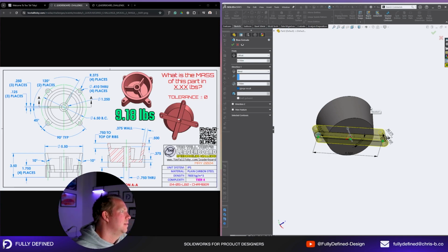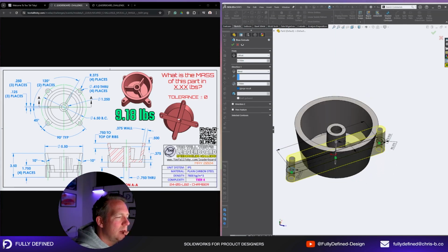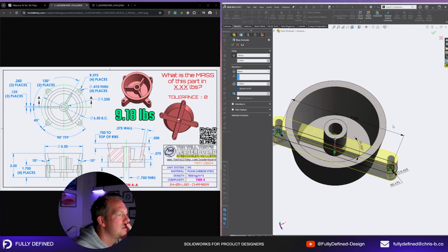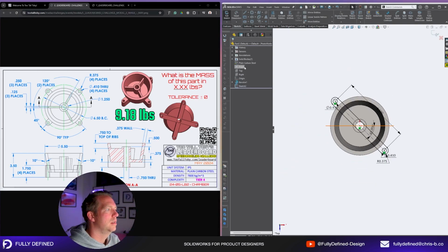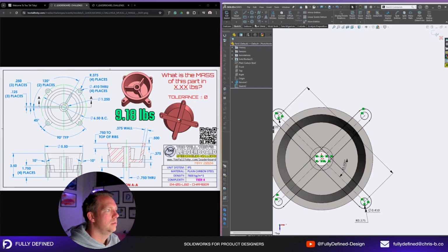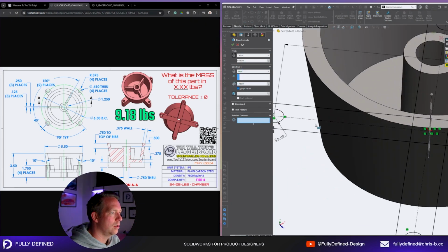Yeah, it's actually a nice complicated model to think about. Yeah, it's a tricky one. I'd really like to go extrude up to next, but up to next won't cut it because it stops at a certain distance. So that won't work. I think we have to go multi-body then and just cut that hole again afterwards, in which case I also want to do the second sketch here, which I can just mirror like so, then do an extrude, put all my measurements in again, select out contours.